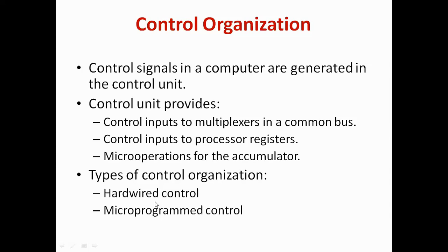And there is another control unit, that is micro programmed control unit, and as the name suggests, it is based on program. So there is a particular segment of memory that we call control memory. In this control memory, some programs are there, and once we execute these programs, control signals are generated.